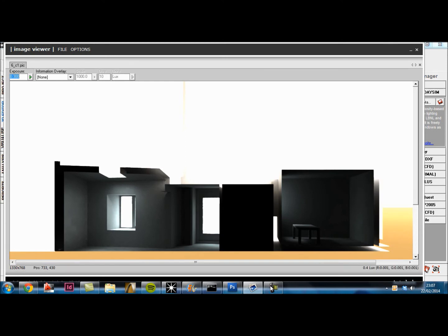And this is a really useful thing because this really then allows you to look at entire buildings. And again, depending on where you set up your camera, if you do it in plan or if you do it in section, it allows you to look at different spaces and different light levels in those different spaces in a way that wouldn't otherwise be possible. And again, we can do the same things we did before. We can look at false color.